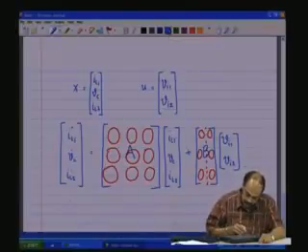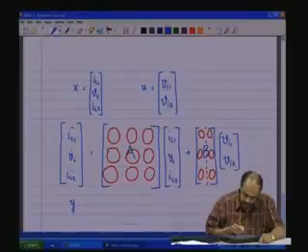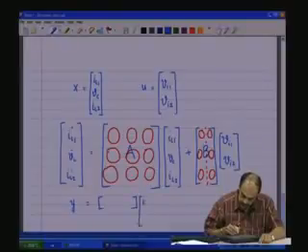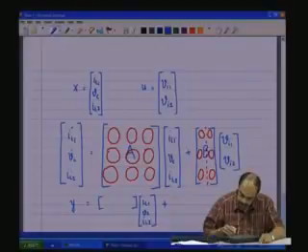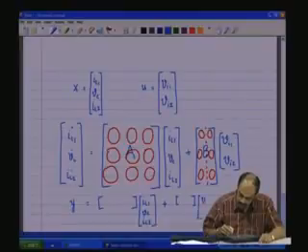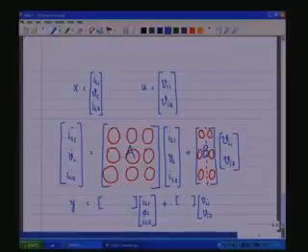and the output Y, whatever the output Y is supposed to be, will contain the C matrix times IL1, Vc, IL2, plus we have Vi1, Vi2, and as there are no direct feed forward terms, that is 0 and 0, and here if it is Vc that we want to consider as an output variable, then it would be this 0 1 0.